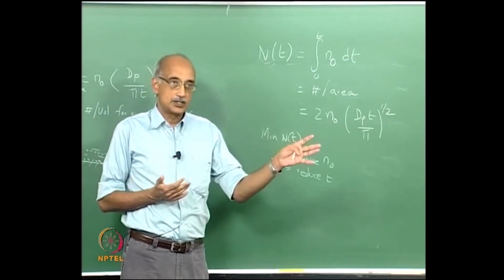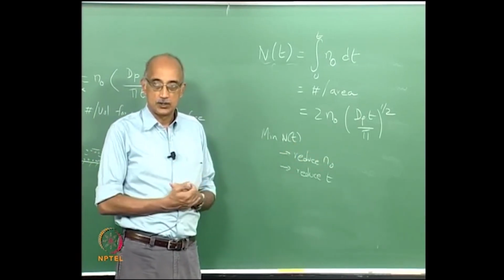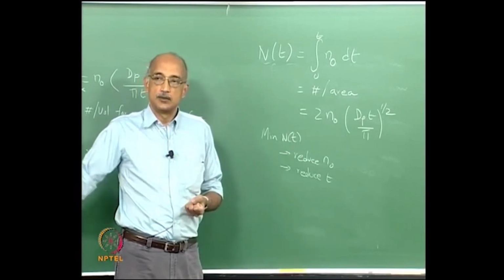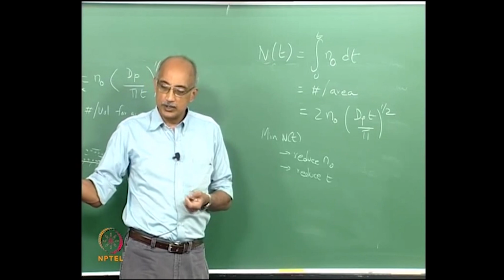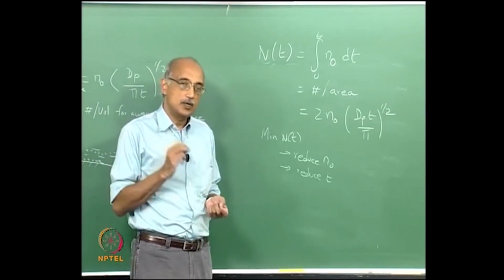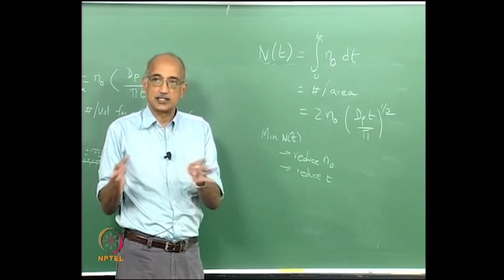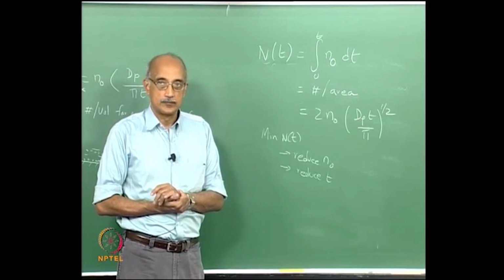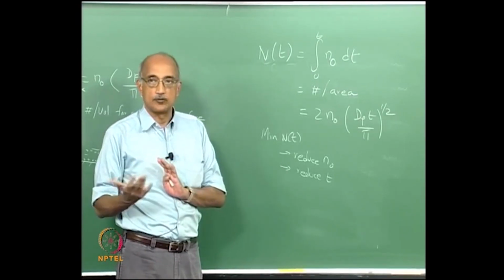The end of the line tells you I'm now ready to make a product, so it pulls components. So once you receive that signal, then you start sending material through your process, and you do it in a fashion where it's a continuous flow, which means there is minimum time of waiting for components to be assembled in the next stage of the process. And what you are minimizing then is what's called work in progress, or WIP.